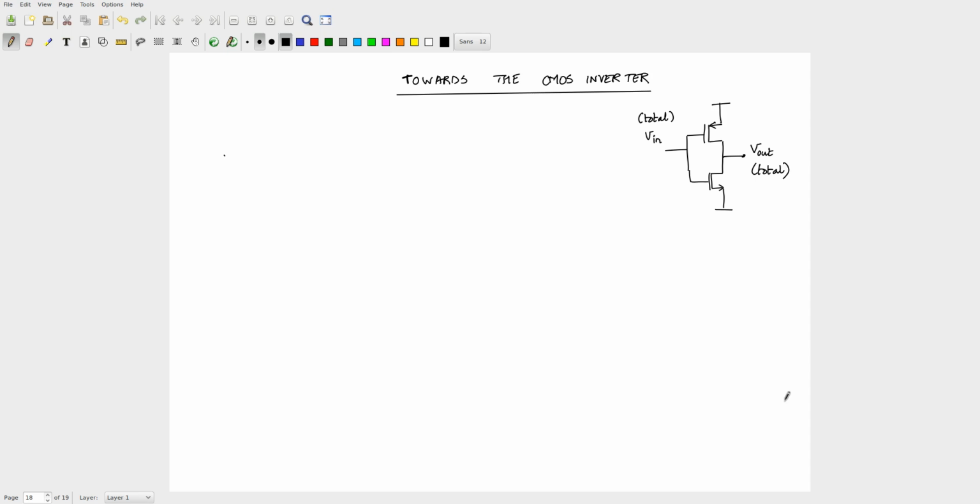Okay. So now let's see if we can get both the PMOS and the NMOS to give you some amplification. So now let me just take this particular incremental circuit. Okay. And let me say I have something here. Let me call that some GM. Let me not say what that is. Alright. GM times VI. This is VI. Alright. And I anticipate two transistors. Let me call them M1 and M2. Right. So I will have two resistors here.